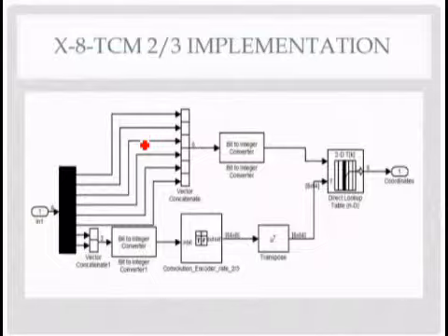You have one subset coming out, but since there are 8 subsets for 2/3, each of the subsets is 64 by 8. So again the last 2 bits produce a subset, and then the first 6 bits select which point on the subset is to be transmitted. And then on the receiver's end, we use the Viterbi algorithm, and Tyler is going to explain what that is.